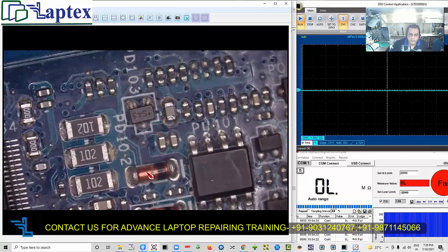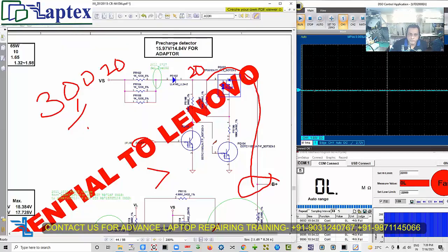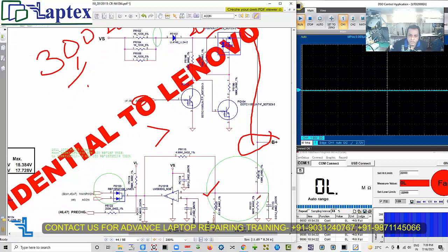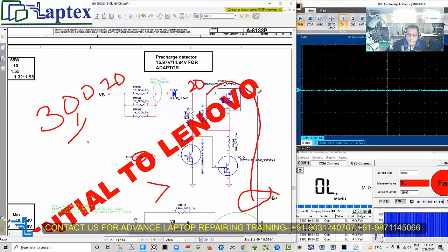Now the diode could be faulty, or wherever it is going could be faulty. So let's begin by removing PQ102. If there is any problem on this side, like a shorting or something not okay, it will go reverse, and this diode is switching through this area, and it could stop this voltage from going ahead. So now remove this PQ102 first.